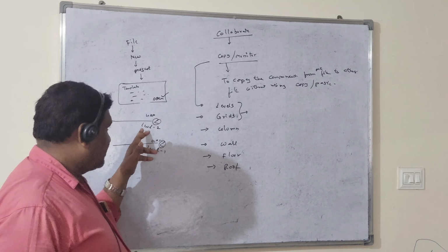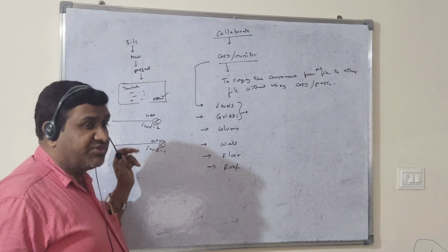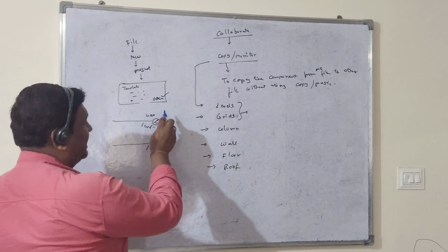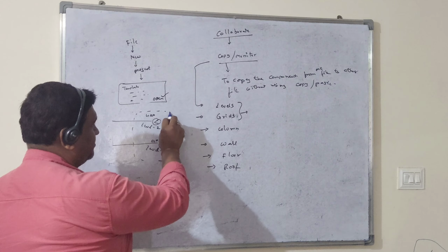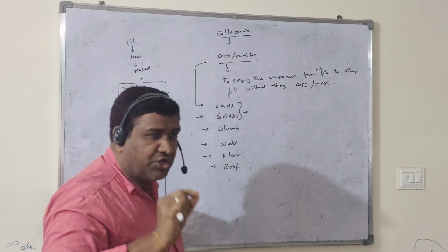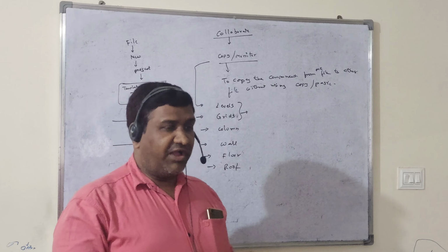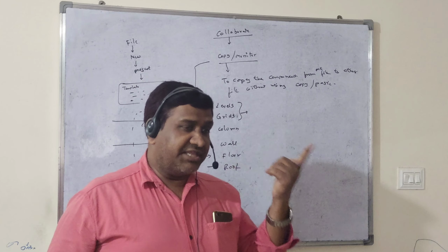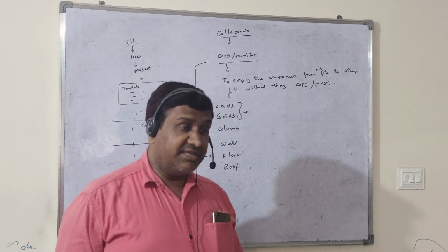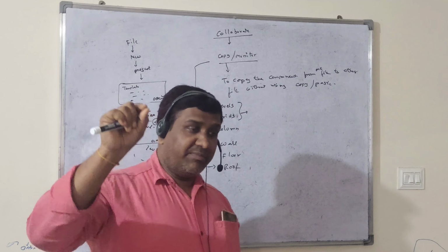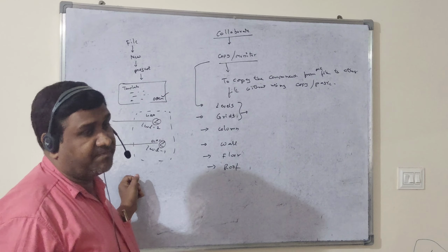After taking it, whatever levels you find in the north elevation, level 1 and level 2, you have to delete these 2 levels first with the help of window selection. Click and drag. Don't go with a single click. If you single click, one level will be deleted, but the other level will not be deleted. Single click delete is not possible here. You have to use window selection, click and drag, and select both levels at a time.